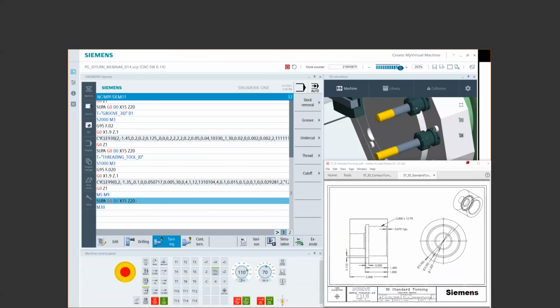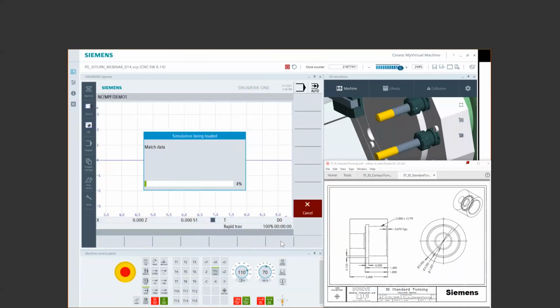So you never want the machine sitting without the known tool having its offsets. Previously, this wasn't an issue because I was driving right into a tool change, and in my tool change, I was going to have the D1 anyway, right? But when I'm doing this as an end of program, I like to make sure that I reactivate the cutting edge that's loaded, or spin your turret to a location that has no tool in it. That's another option. We do a final sim, and we should have a complete part.